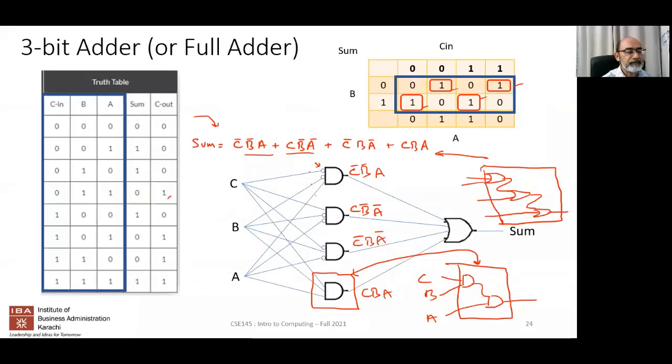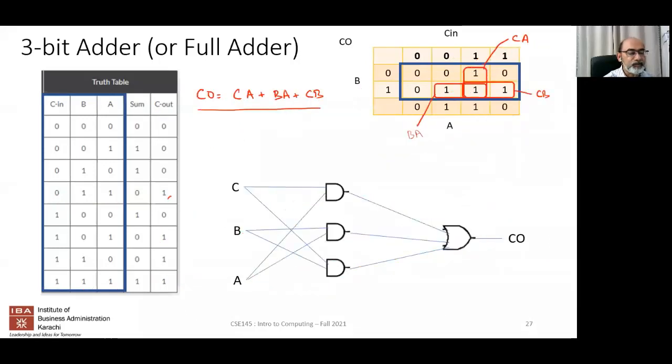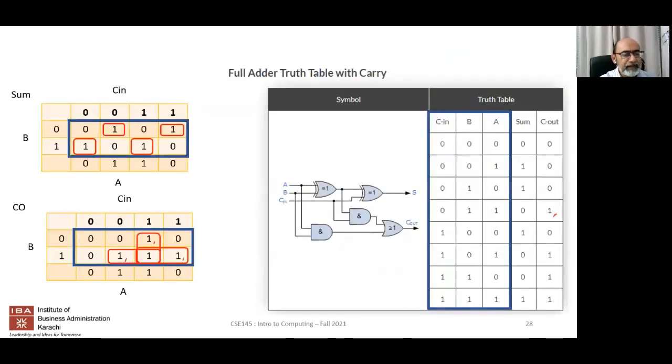If you look at this, there are a total of at least 7 gates, and then several NOT gates, 7, 8, 9, 10, 11, 12, 13. So this probably has something of the order of 13 gates being used over here. If you combine both of these expressions together, you have 13 plus 5, about 20 gates or so being used. Now, I'll show you a solution, a representation of the actual solution that is used in the industry. As was earlier pointed out by one of your colleagues, it has 2 XOR gates.